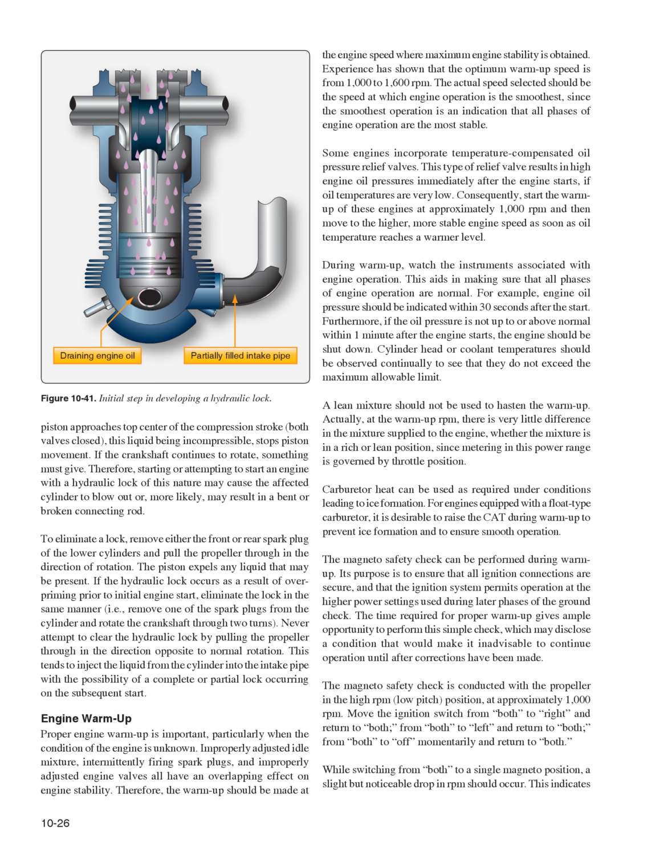Engine warm-up. Proper engine warm-up is important, particularly when the condition of the engine is unknown. Improperly adjusted idle mixture, intermittently firing spark plugs, and improperly adjusted engine valves all have an overlapping effect on engine stability. Therefore, the warm-up should be made at the engine speed where maximum engine stability is obtained. Experience has shown that the optimum warm-up speed is from 1000 to 1600 revolutions per minute. The actual speed selected should be the speed at which engine operation is the smoothest, since the smoothest operation is an indication that all phases of engine operation are the most stable.